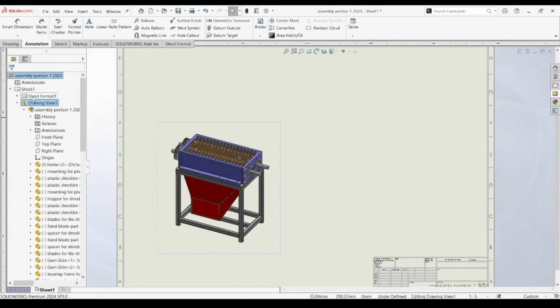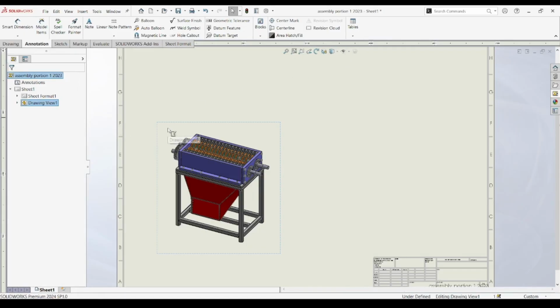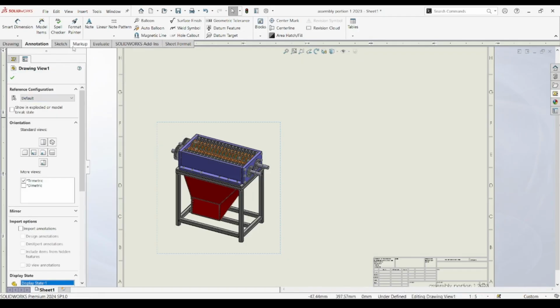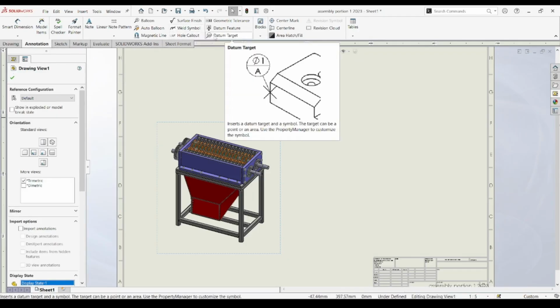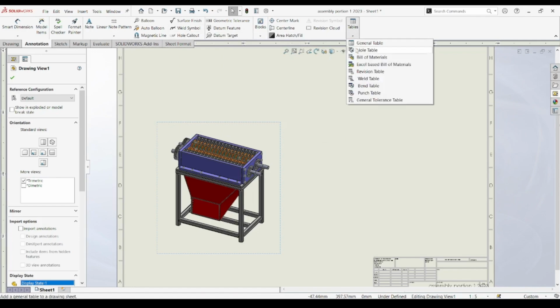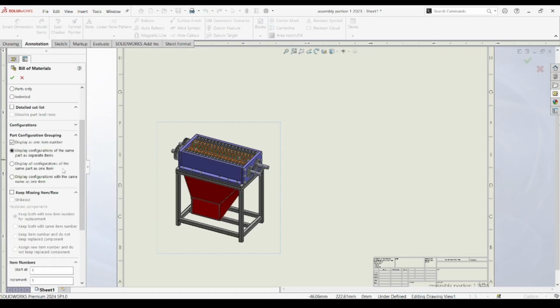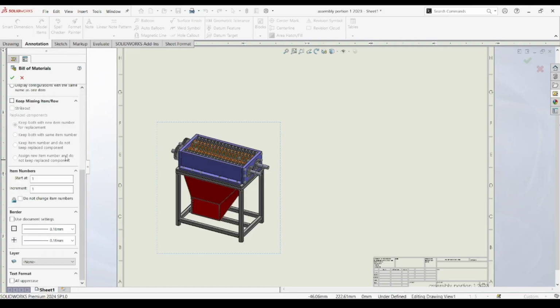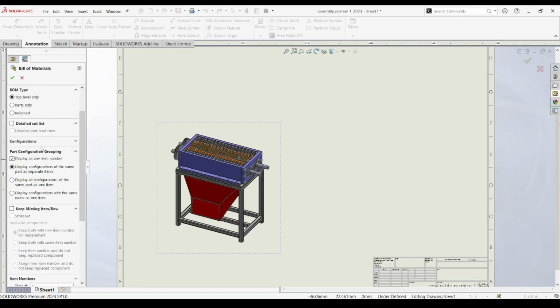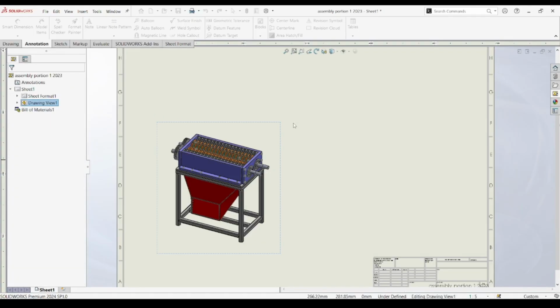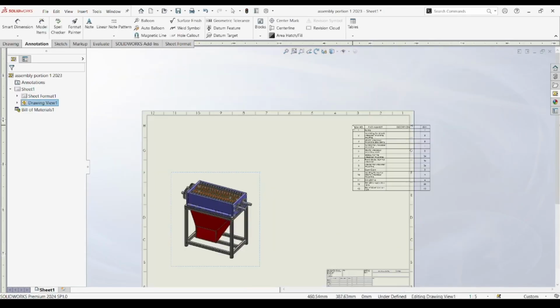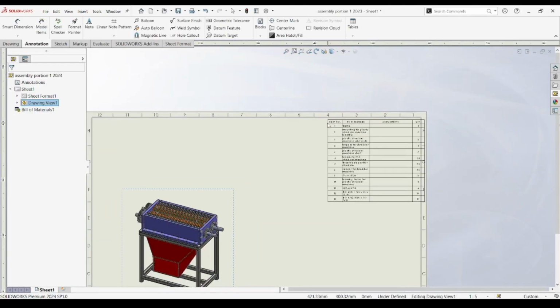One major point we address is the difference between structured and flat BOMs. A structured BOM reflects sub-assemblies exactly as they're built in the CAD hierarchy, which is helpful for organized assembly steps. A flat BOM, on the other hand, lists all components as a single-level list, regardless of sub-assemblies. Depending on your fabrication approach, whether you're manufacturing in-house or outsourcing parts, you'll choose one over the other.